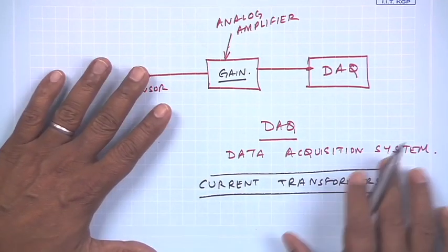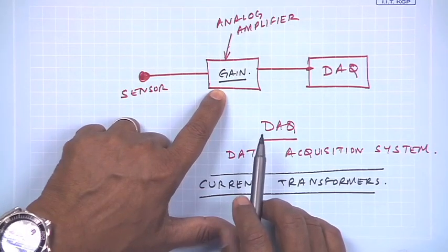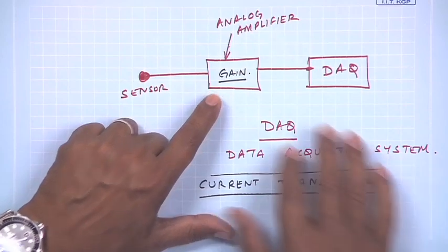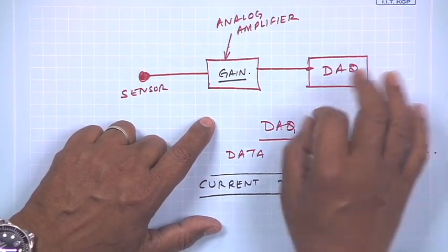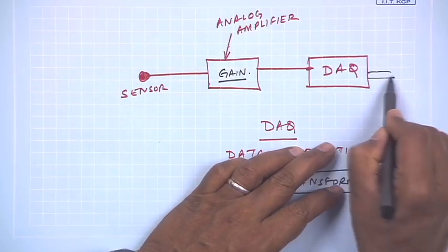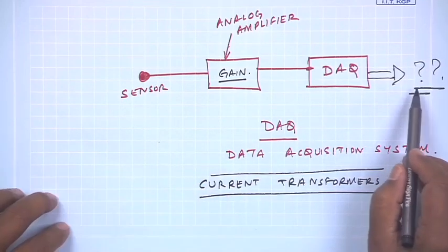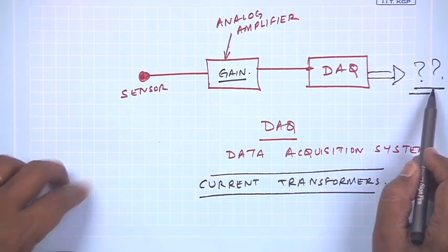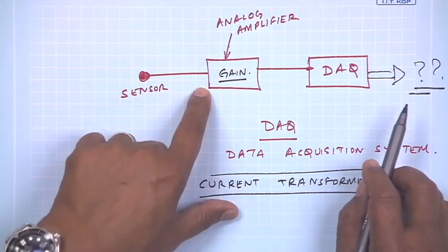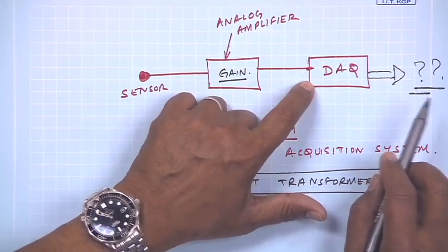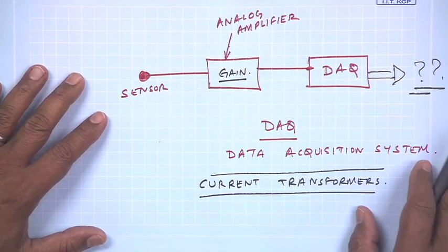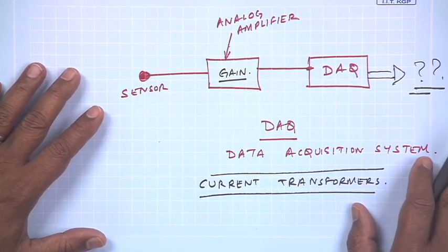So, this numerical establishes how a particular gain could be found, so that the data acquisition system is able to sense the signal. If I cannot sense the signal, I will not get anything meaningful; I would otherwise get garbage, if it is not able to hit the minimum noise floor of this device. That is what one has to be careful about in such systems.